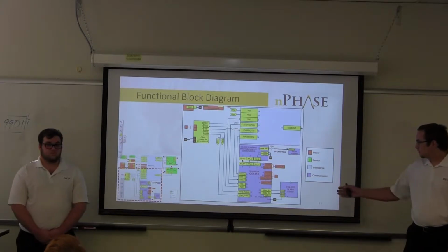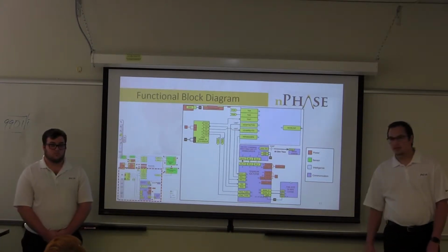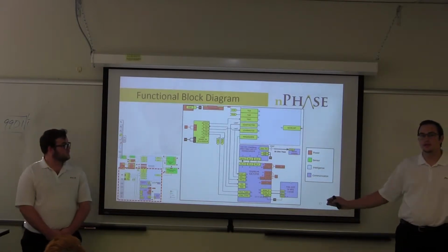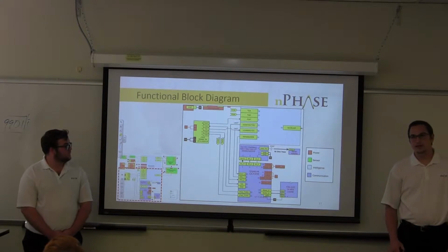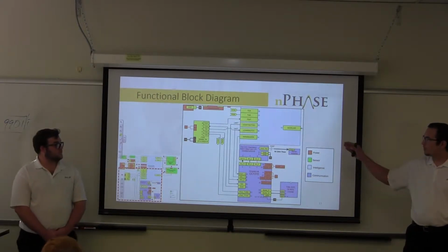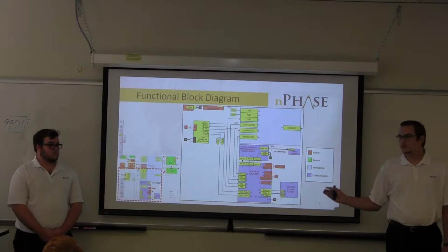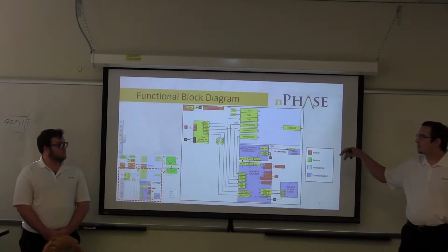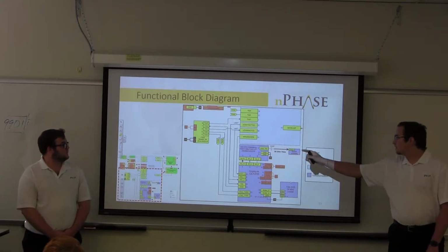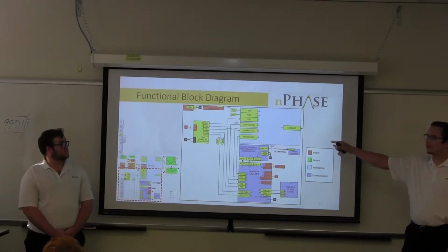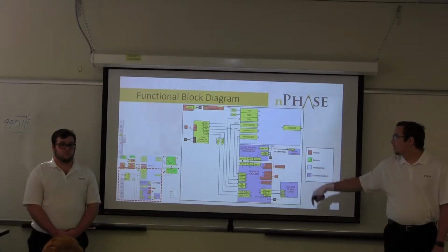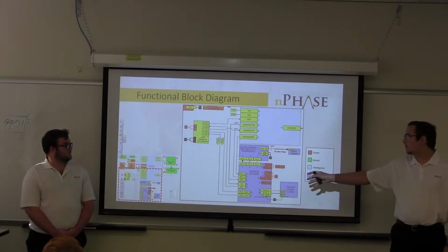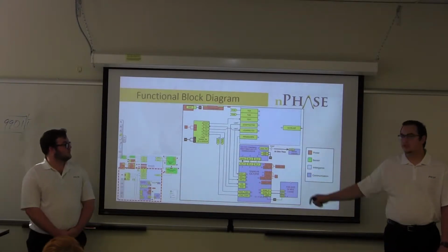Next, we have our CC1310, as well as its connection to the MSP430. Over there, we have our JTAG, and CC1310 is another microcontroller, so we're actually doing daisy chaining, so we can program both microcontrollers, the MSP430 as well as the CC1310. We're doing so by having the TCK and TMS lines tied to both of them, and then we have the TDI line of the JTAG header going to the MSP430, and the TDO line of the MSP430 going to the TDI line of the CC1310, and then that TDO line going to the TDO of the JTAG.